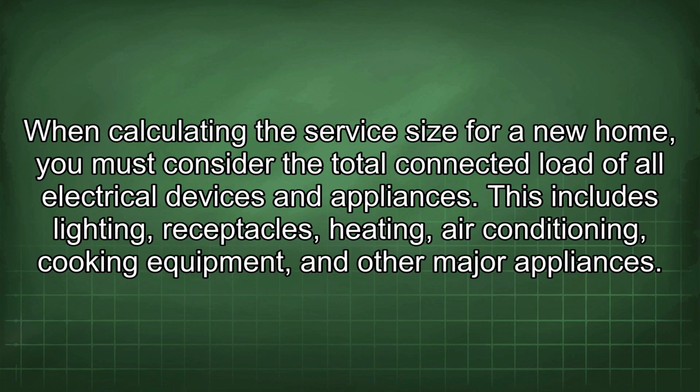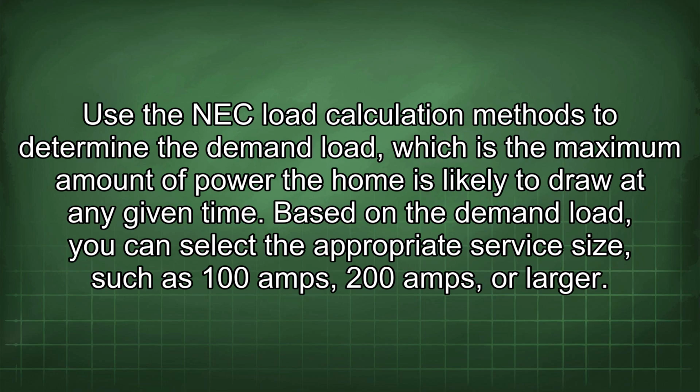When calculating the service size for a new home, you must consider the total connected load of all electrical devices and appliances. This includes lighting, receptacles, heating, air conditioning, cooking equipment, and other major appliances. Use the NEC load calculation methods to determine the demand load, which is the maximum amount of power the home is likely to draw at any given time.